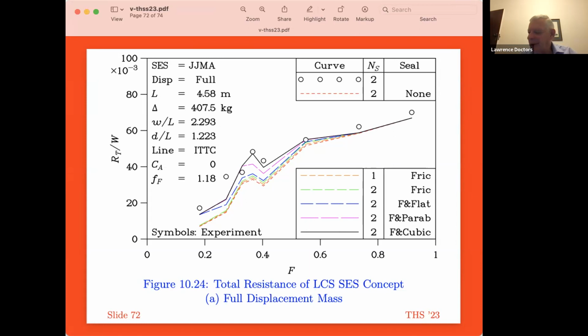I do have a friend in the US, whose name has just escaped me at the moment, who did a PhD on the subject, but I thought he was awfully brave doing research on trying to work out the actual way the finger collapses on encountering the water surface. He got his PhD, but he ended up working on a very, very simplified version of the problem. So I think some of these hovercraft problems, particularly the skirts, almost defy full proper analysis. They're so complicated. And as was just suggested, perhaps even just a full-scale experiment is the simplest way to find out what's the best design.